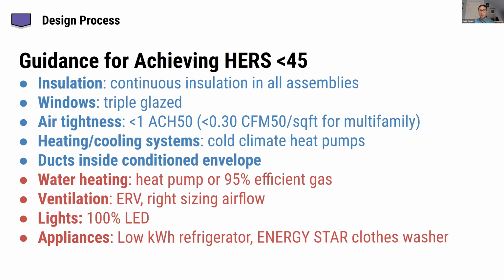And then heating and cooling systems. Sometimes designers will say, you know, I've got a 98% gas heating system. That's about as good as it gets, right? However, heat pump systems, the most efficient heat pump systems will use less energy and get a better HERS index than the most efficient fossil fuel systems. And that's primarily because heat pump systems don't have to make heat. Instead they move heat from one place to another. So they can gather heat from the outdoors and bring it into the house more efficiently than you can create heat.